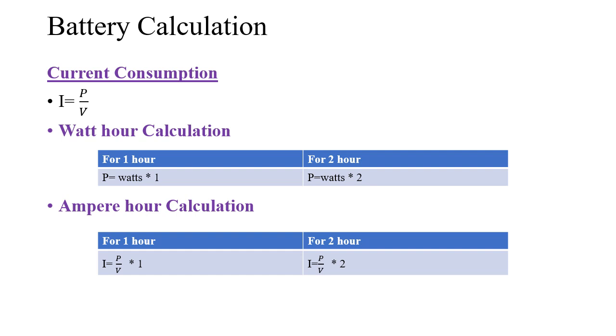Now we are going to calculate the capacity of the battery. The rating of the motor is 250 watts, which is what we calculated and concluded. For a 250 watts motor, let's consider three cases for choosing a battery, because it depends on the voltage.